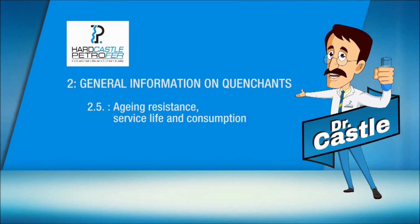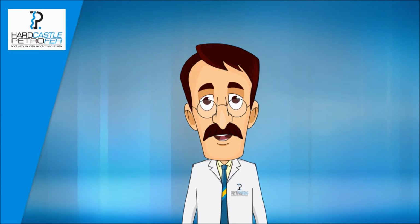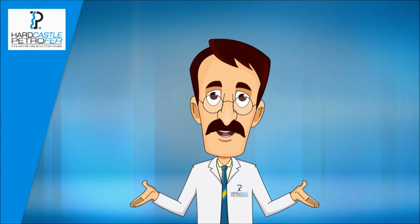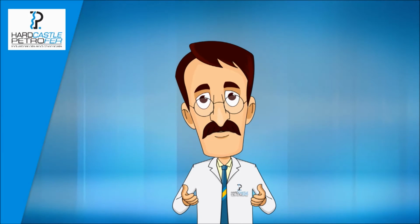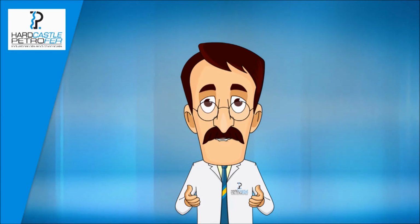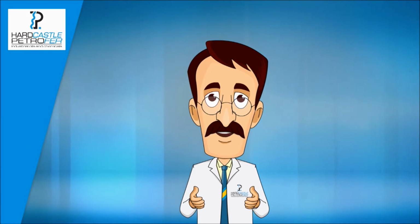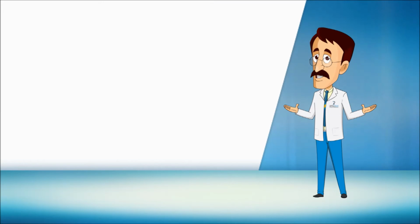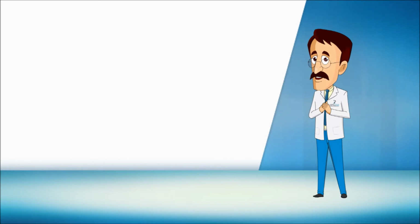Now let's move on to a discussion on the aging resistance, service life, and consumption of quenchants in the process. Resistance to evaporation has a considerable effect on consumption and thus on oil bath economics. Experience has shown that on batch quenching, probably more oil is lost through evaporation than through drag-out by the components. Aging resistance is, however, of the greatest importance in determining the economics of any oil bath.